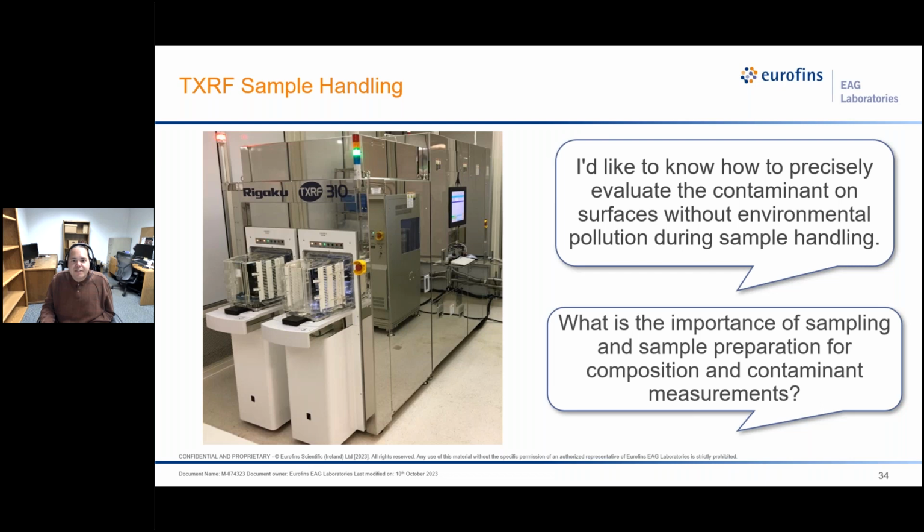So with the technique being so surface sensitive, I wanted to make sure to answer some of the questions we received on sample handling. With TXRF, we are very surface sensitive. We take a lot of precautions when handling samples. We always recommend that samples are sent to us vacuum sealed and are prepared in a clean room environment. We have our instrument in a class 10 clean room, and we will bring sealed samples as we receive them into our clean room before unwrapping them for analysis.